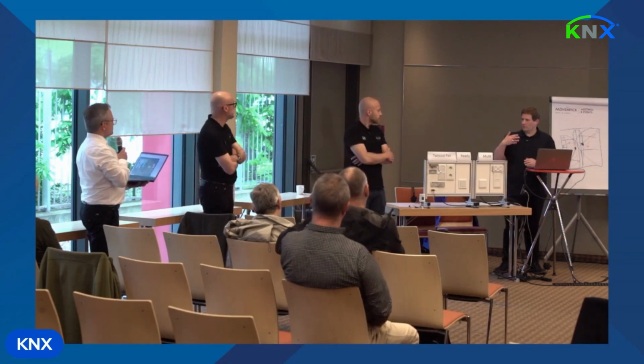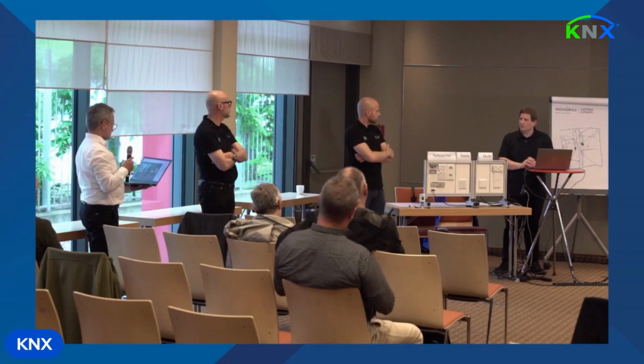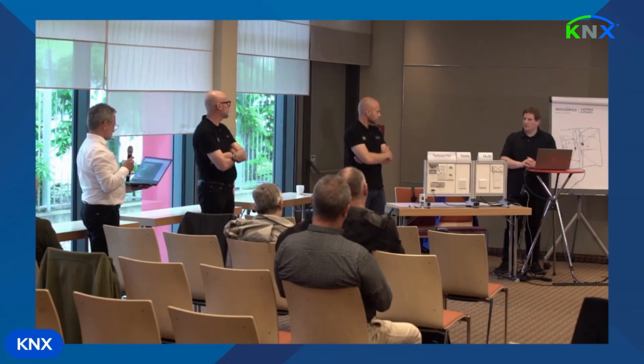Maybe if you refer to physically addressed, so individually addressed telegrams, these new generation of couplers, not only the RF multi media couplers, but also line couplers or IP routers supporting the security proxy functionality, they have, in order to be able to isolate the subnetwork, also this functionality that ETS has enabled automatically. So it's not possible to inject plain individually addressed telegrams from the subnetwork, for example, from radio frequency to the twisted pair. So this protection, filtering and proxying is not only done on group addressed frames, on multicast frames, but also for broadcast and individual frames, in order to protect against somebody trying to inject into your installation.